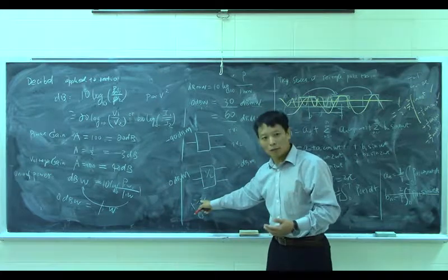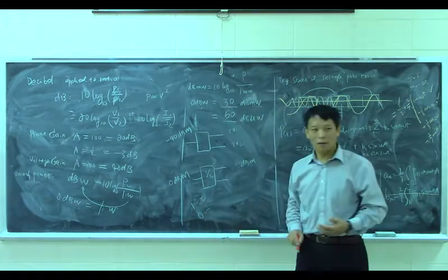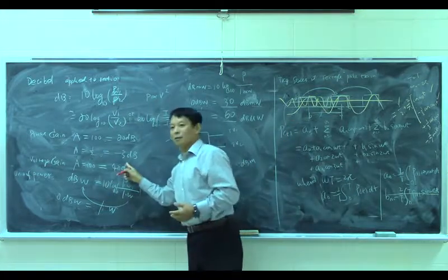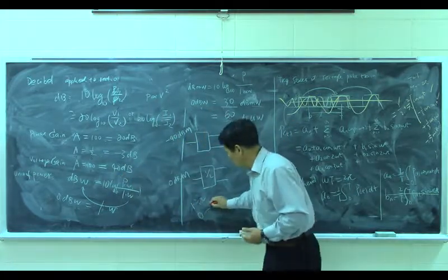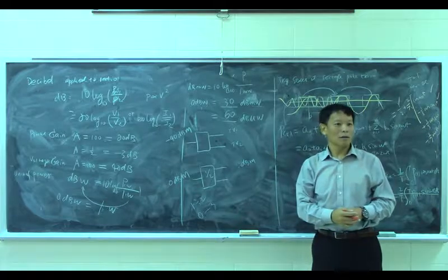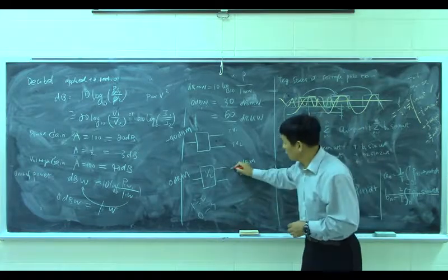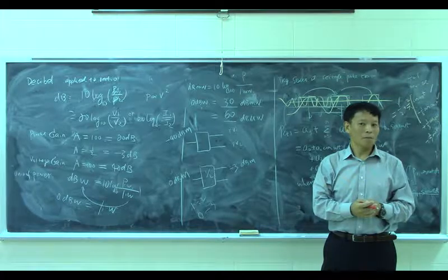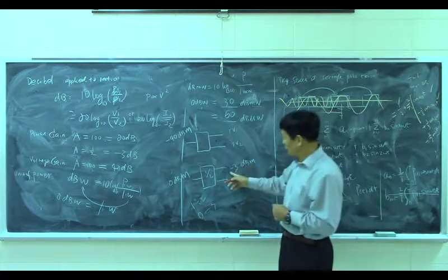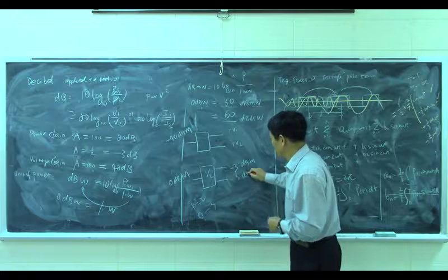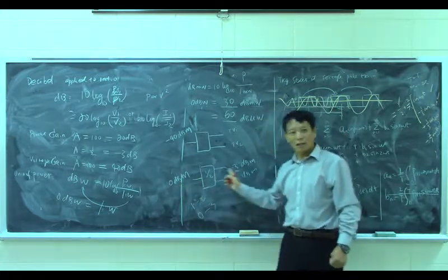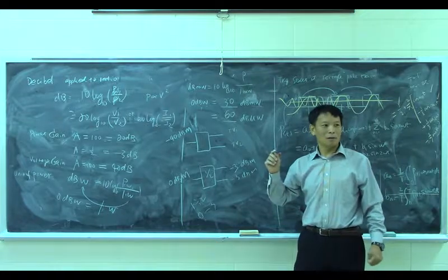You divide it by 2, then you subtract 3. So using minus 3, that's why here we have negative 3 dBW. Both will be negative 3 dB. So 0 in, you get negative 3 here, negative 3 here.